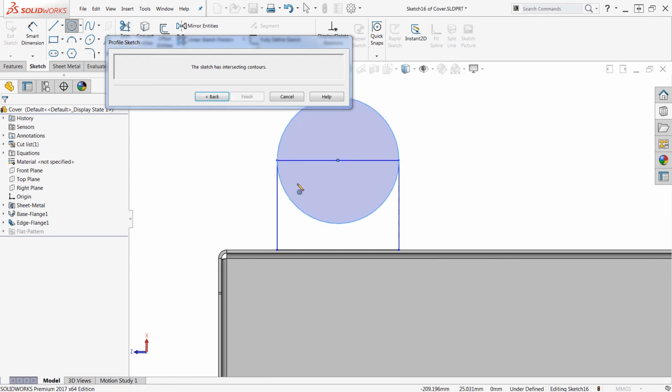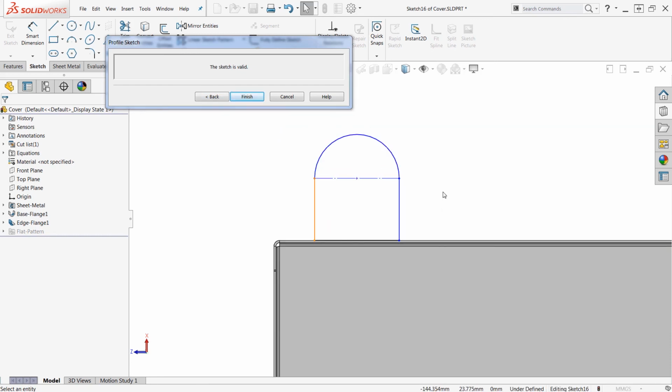So I add a circle in there, swipe for my trim tool, and then select that line and turn it into construction geometry. Now I retain all of those sketch relations just by doing that without having to do a lot of extra editing. All right. I'm going to go ahead and swipe for dimension, and I'll dimension